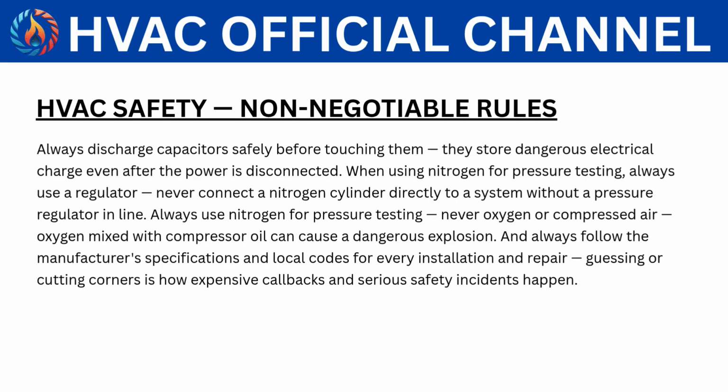Always discharge capacitors safely before touching them. They store dangerous electrical charge even after the power is disconnected. When using nitrogen for pressure testing, always use a regulator. Never connect a nitrogen cylinder directly to a system without a pressure regulator in line.